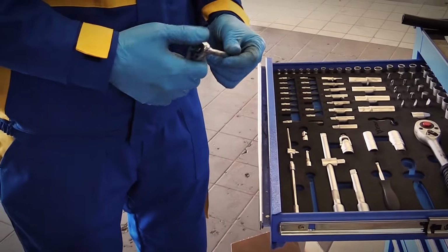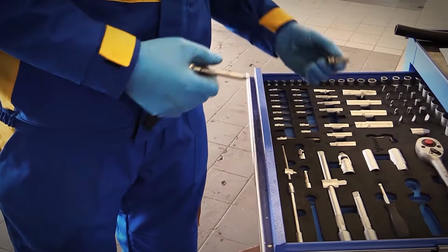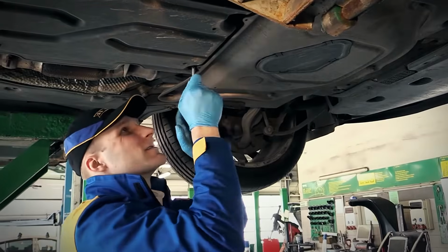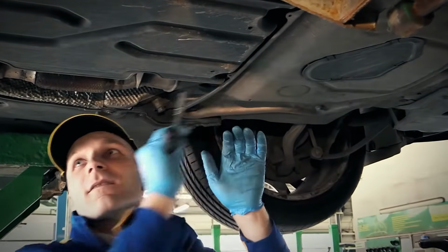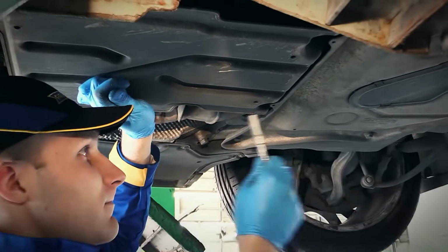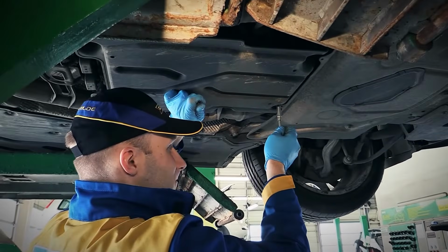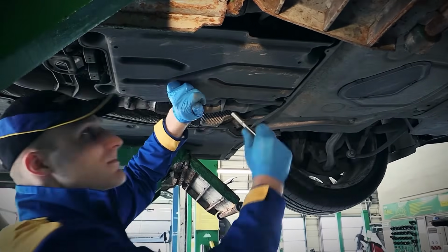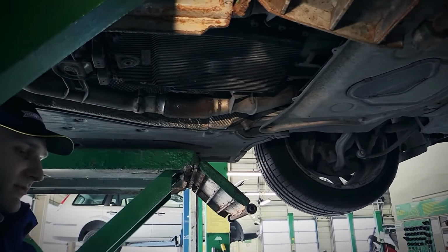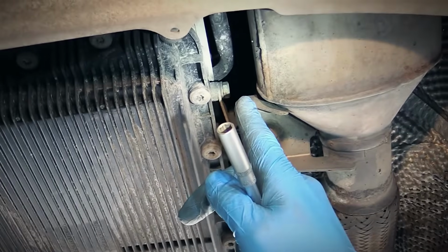The device is able to produce a pressure of 10 bar, which is sufficient to push the oil through a thermostat, heavily soiled ATF fluid cooling devices, or blocked filters. Automatic transmissions which are equipped with a thermostat are the exception. In this case, the device must be connected in between the automatic transmission and the thermostat. Otherwise, the dynamic oil change process may not be carried out.